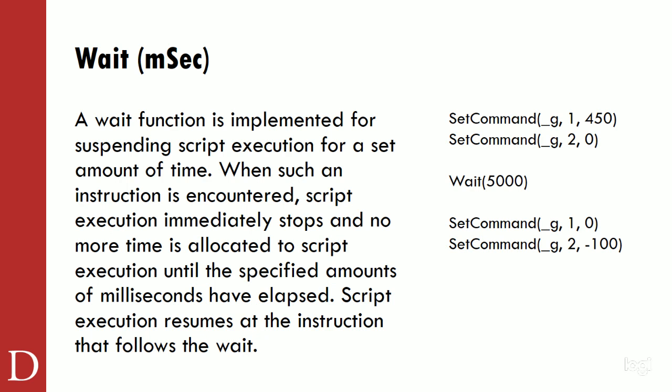Again, we're in mixed mode. This is going to tell me to drive straight. So I hit that code first. I start driving straight. My minibot is driving like this. And now he's over here somewhere. And he does that for a total of 5 seconds, right? So this is 5,000 milliseconds.